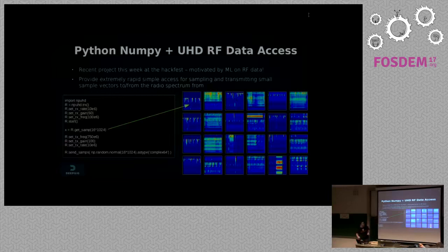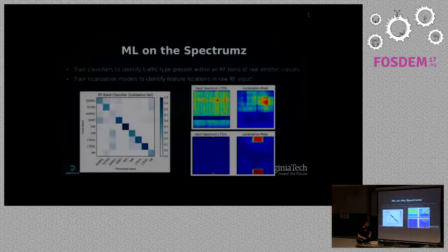What we're doing here makes it really quick to take little looks all over the spectrum and generate spectrograms for them. If we do that, we can start to get all these samples of different bands that are all around us. This is just a sampling of a bunch of spectrograms across common bands. If we use this in a ConvNet, we can also build a classifier for the different bands. This is not a very good one at the moment, but that's just because the slides were a bit late.